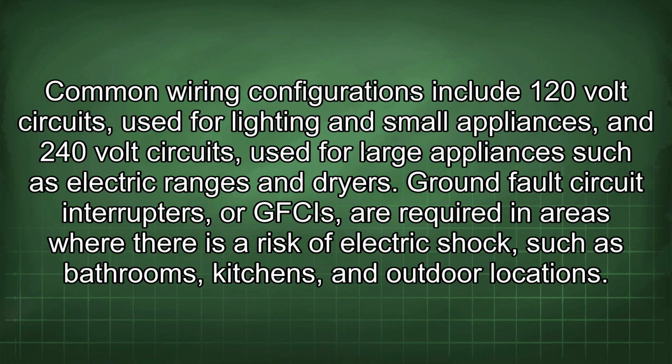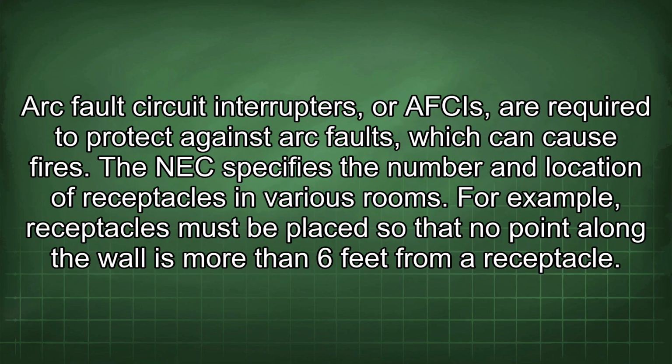Ground fault circuit interrupters, or GFCIs, are required in areas where there is a risk of electric shock, such as bathrooms, kitchens, and outdoor locations. Arc fault circuit interrupters, or AFCIs, are required to protect against arc faults, which can cause fires. The NEC specifies the number and location of receptacles in various rooms.